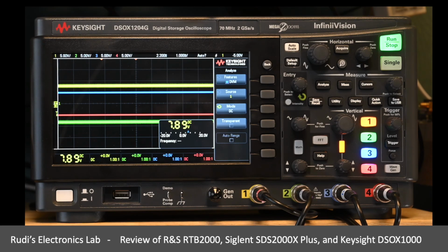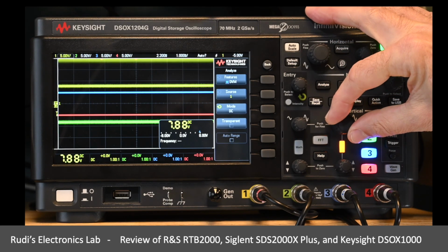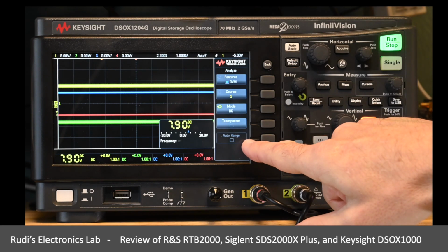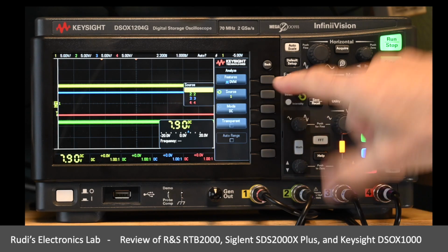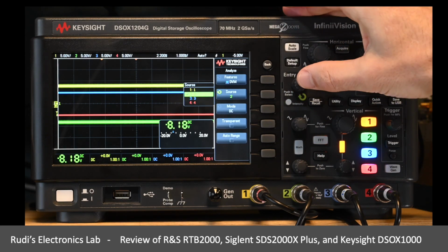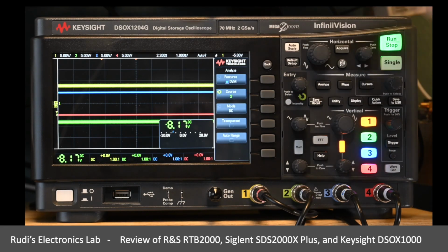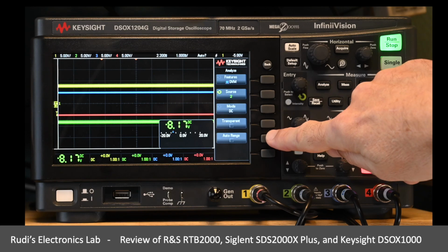Now, in terms of the measurement range, there are a couple of things more to note with this device in order to use it properly. As I just explained, we can basically select here via the analog channel. However, we also have an auto range function that we see here. And actually, if I go to channel number 2 here, then the auto range activates itself. Why was it not available on channel 1? Well, the auto range is not available for channels that are selected for trigger, for whatever technical reasons. If a channel is not selected for trigger, then the auto range basically is available.